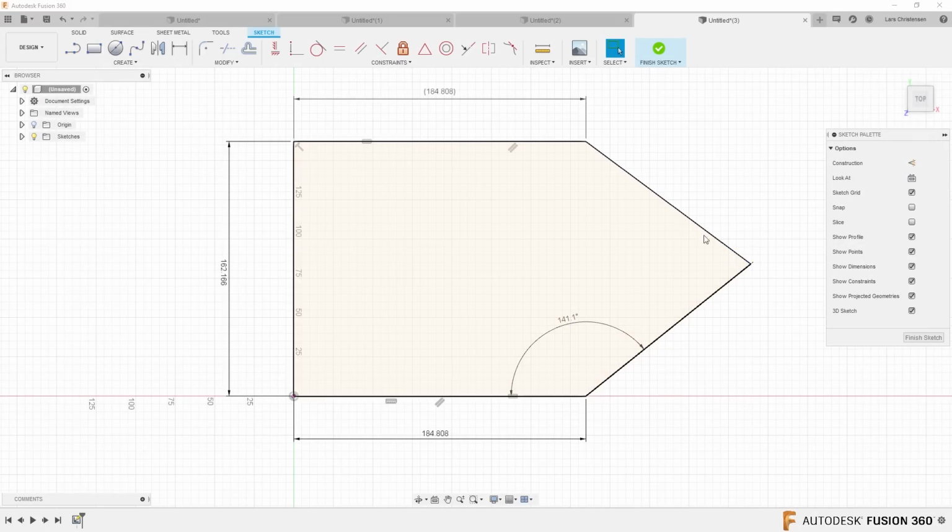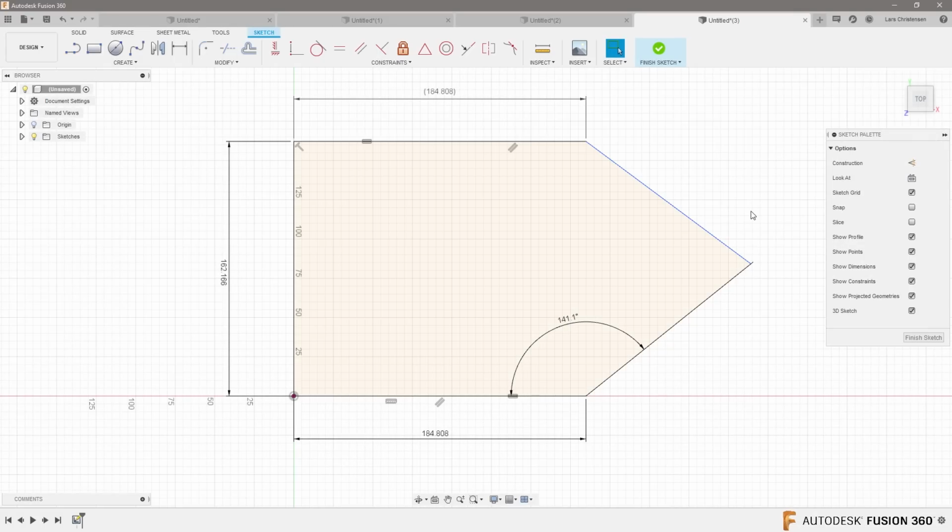The other thing you can do if you have a blue segment is you can right click on it and you can say fix it. And then it's actually going to turn green. What that means is that now it's locked and this is not going to move. It's glued to the background. That is probably the most secure thing.